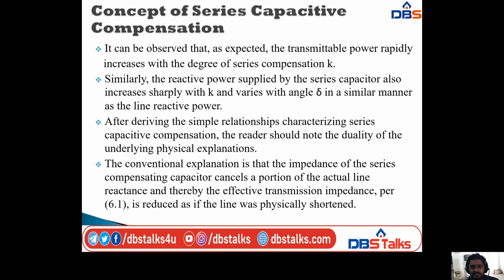So the conventional explanation is that the impedance of the series compensating capacitor, that is X_C, cancels a portion of the actual line reactance, and thereby the effective transmission impedance, that is X effective, is reduced as if the line was physically shortened.